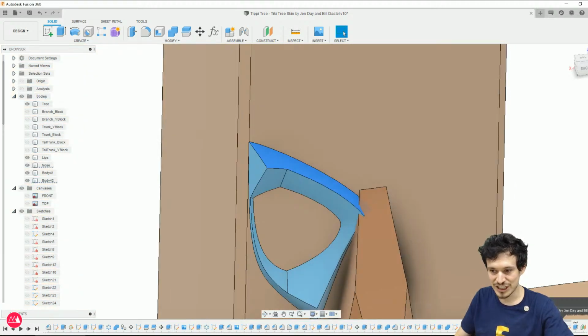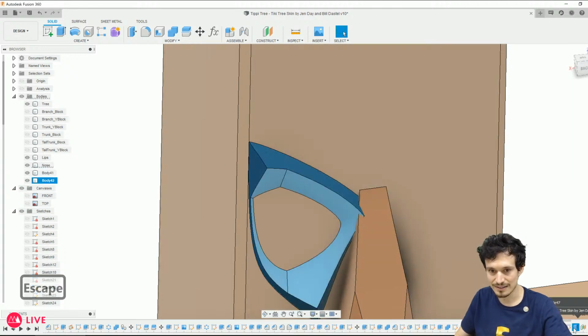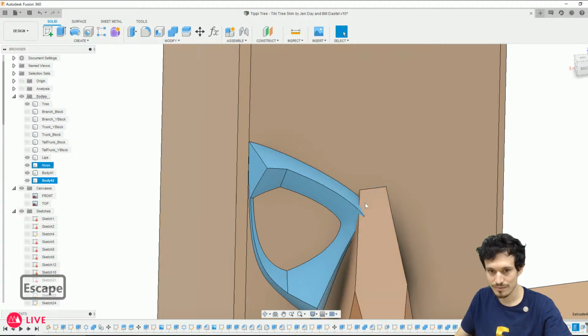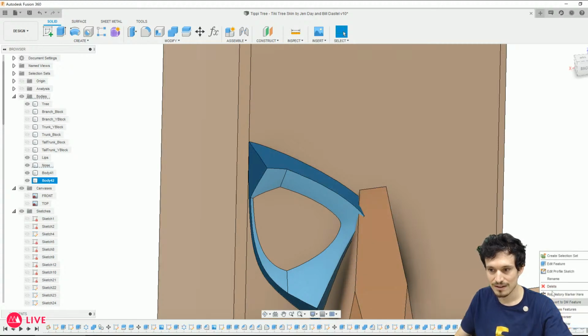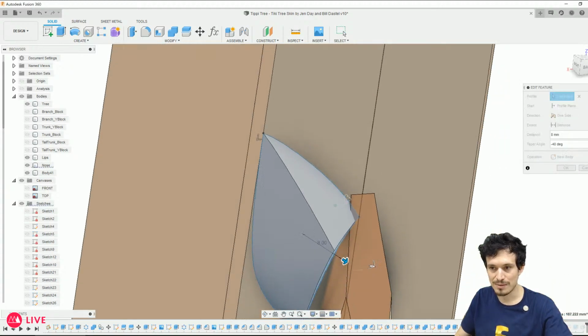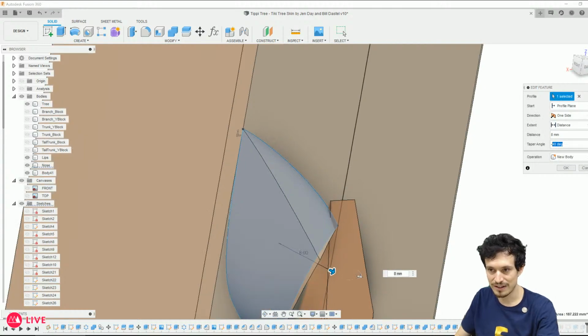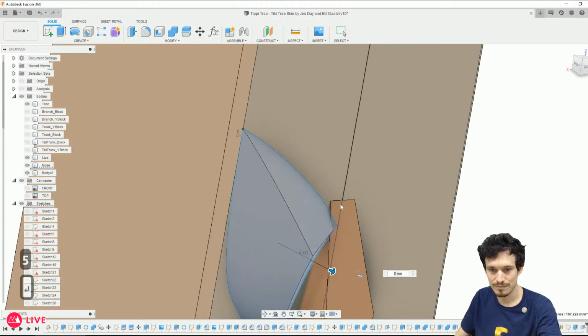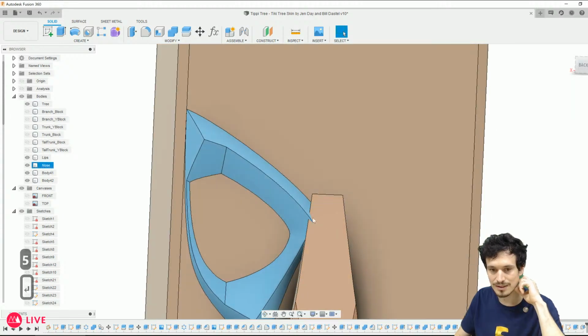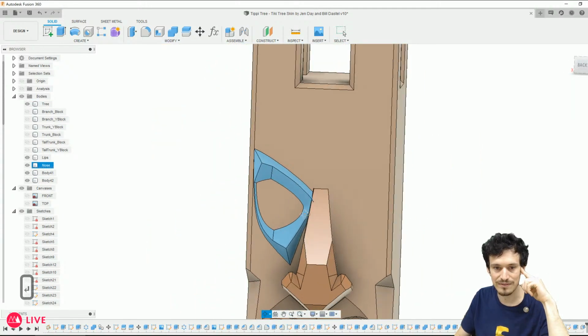Let's see what happens if I change the draft angle of the first part. Where's that one that I did? Yeah, right here. Maybe I want it to be more shallow. Maybe I do want a 45. It's still peeking into the nose a bit.